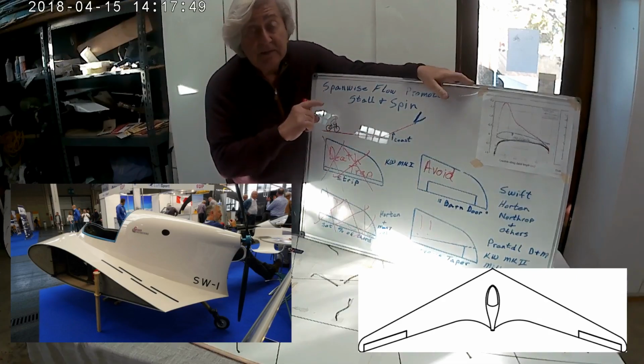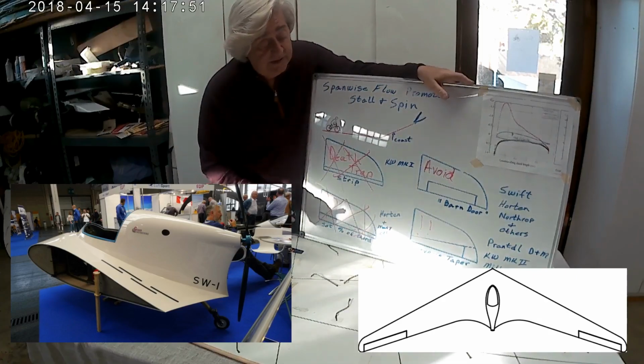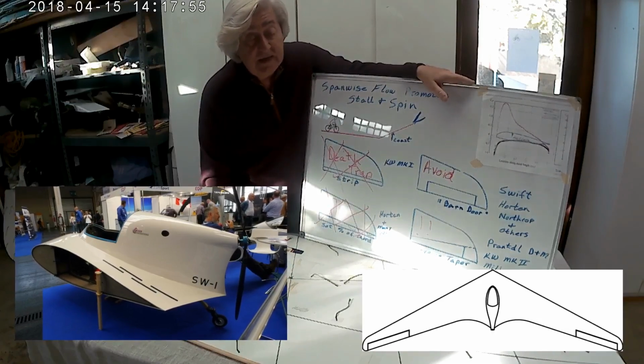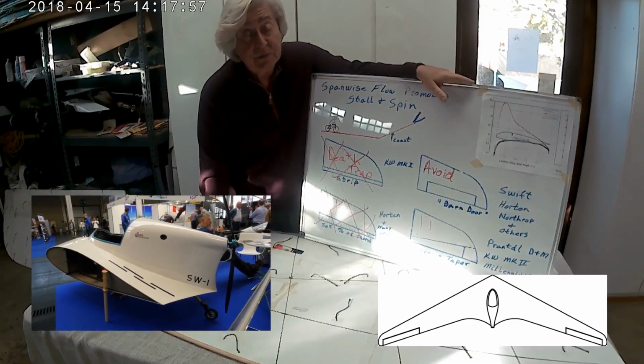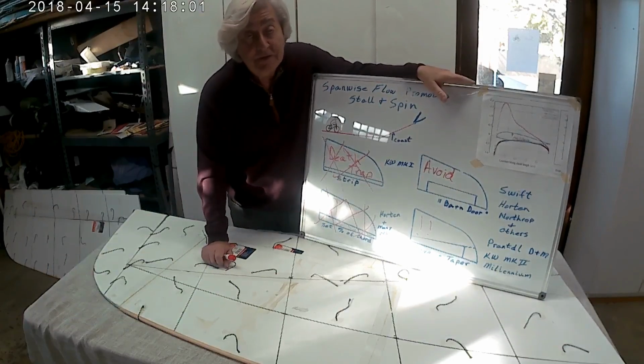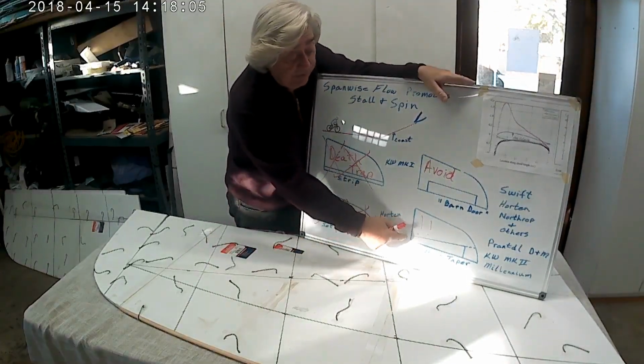He's got an elevon out at the wingtip that looks just very conventional. And I would say, if you haven't built those wings yet, all the way done, even if you have finished them, if you finished them, throw them away. Build new wings. Get the reverse taper.